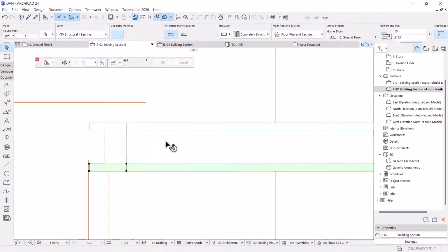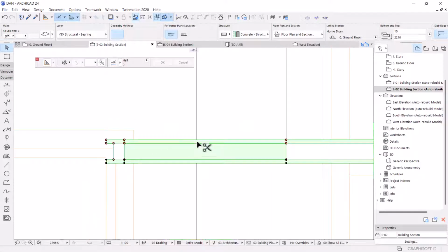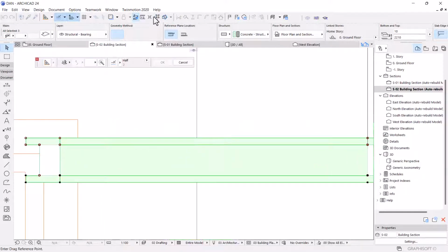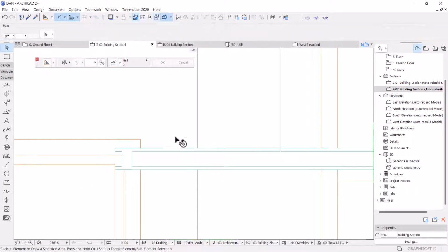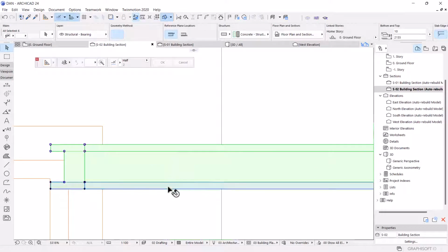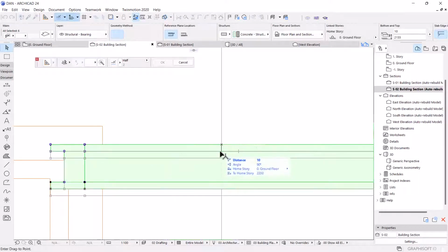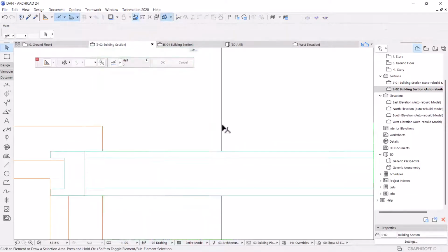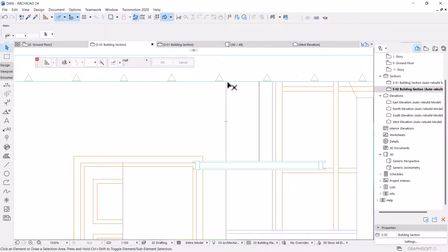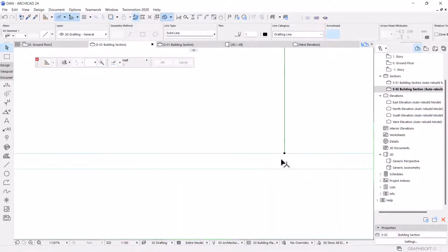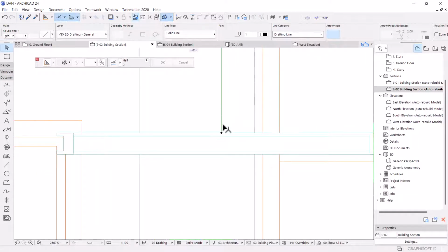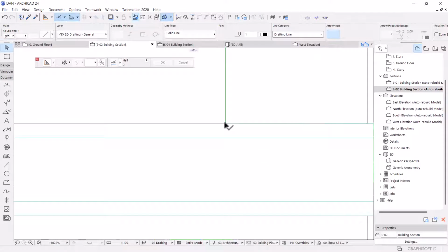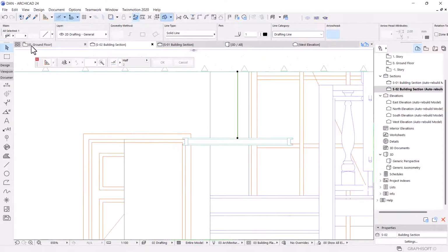Then we can click the three of them, and now let's first enter the suspension of groups, and now I can click those two and this one, and I'm just adjusting them to be where we've just drawn a line here that was 600 millimeters from the top. So I just want them to be where that line ends from 600. Then we have these ones, and now I'm done with them.